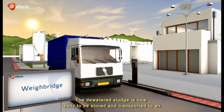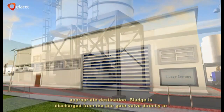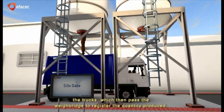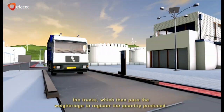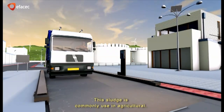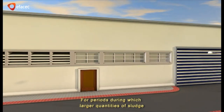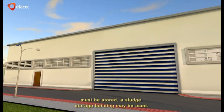The dewatered sludge is now ready to be stored and transported to an appropriate destination. Sludge is discharged from the silo gate valve directly to the trucks, which then pass the weighbridge to register the quantity produced. This sludge is commonly used in agriculture. For periods during which larger quantities of sludge must be stored, a sludge storage building may be used.